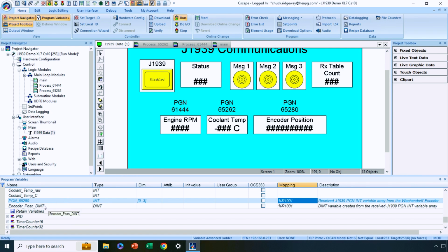So it's a little bit of a trick here to take byte data that's packed into words and copy it over into basically a double integer variable. The Horner all-in-one controllers effectively have 50,000 available registers, which normally you don't have to worry about. Normally, variable mapping just happens in the background, but occasionally you need to send data out over Modbus or something of that nature, and in this case we're doing a little bit of a mapping trick, so that's another scenario where we use registers.